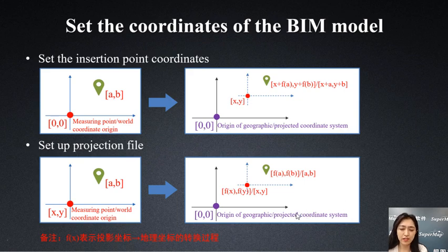If it's a local coordinate system, first we should set it to the value of the local coordinate system, or use the local coordinate system projection file to export and import the data, and then convert it to WGS84 according to the offset of the local coordinate system, or the 4 or 7 parameters conversion method.